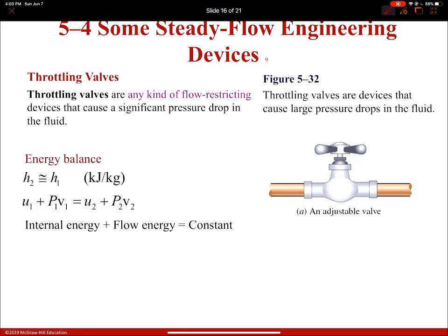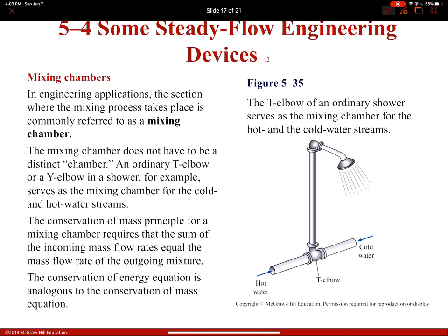Pretty much they are any kind of flow restricting devices that cause a significant pressure drop in the fluid. Okay, that's the most important thing. H2 equals H1. If I keep developing the equation, you know that enthalpy equals internal energy plus pressure times specific volume. Same thing coming in or coming out.